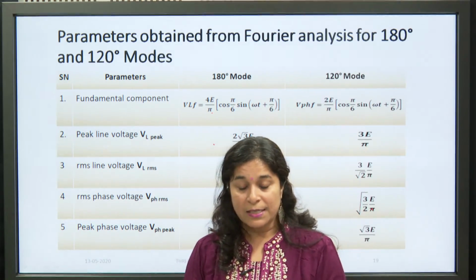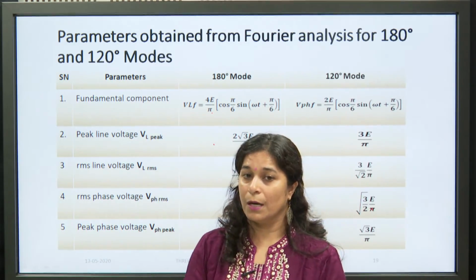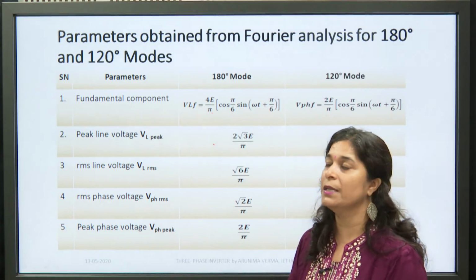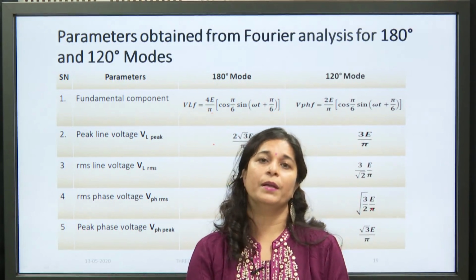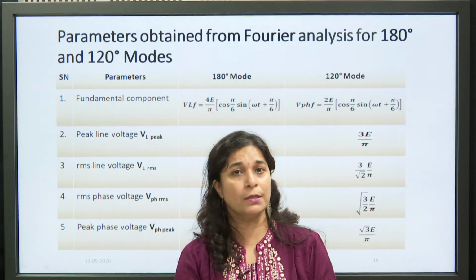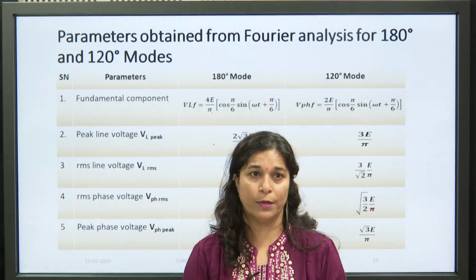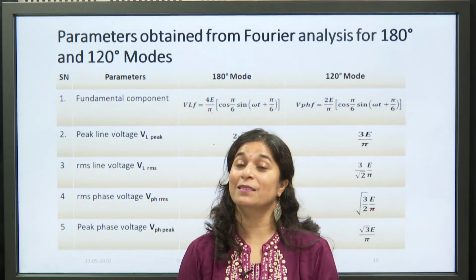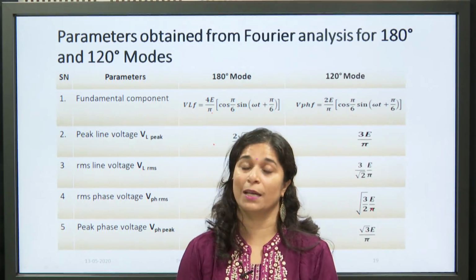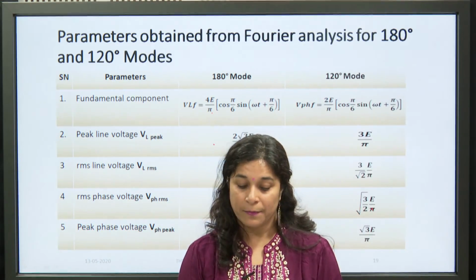This technique has another added advantage, which we will discuss in some other lecture: we will see how the PWM technique controls the output voltage of the inverter, and how it helps in managing, minimizing or mitigating the harmonics as well.